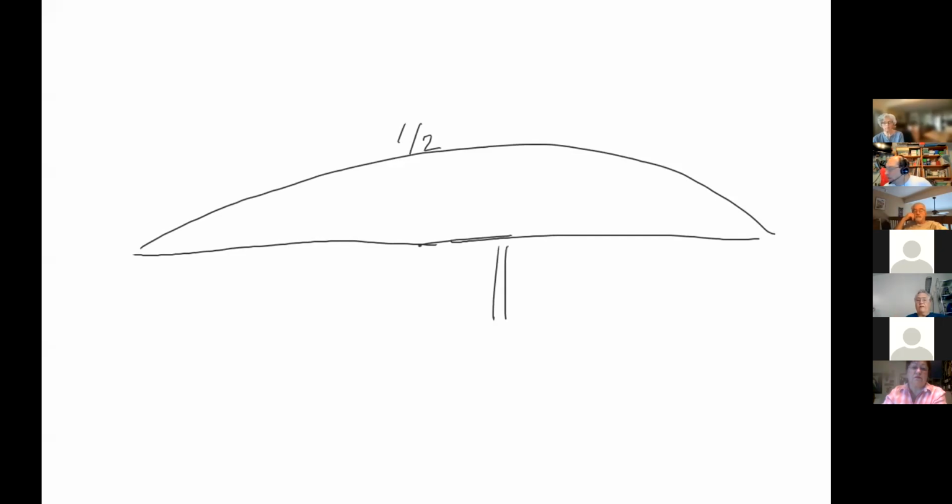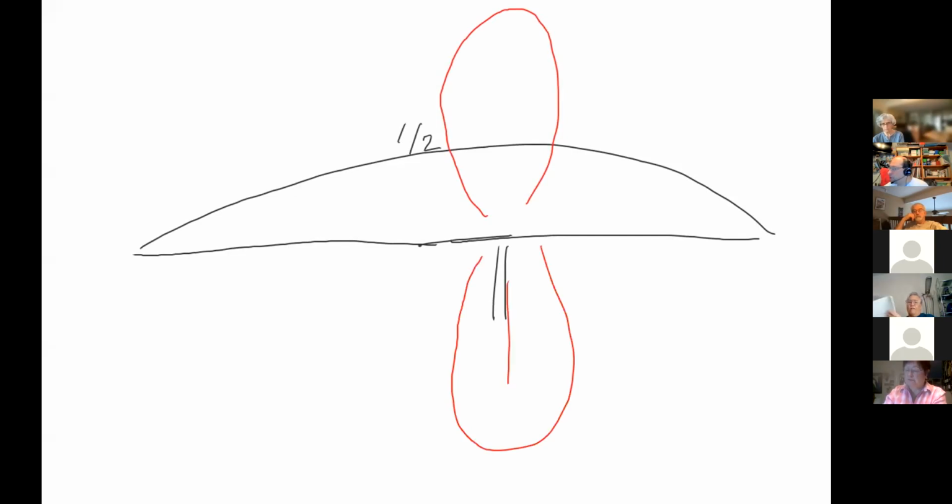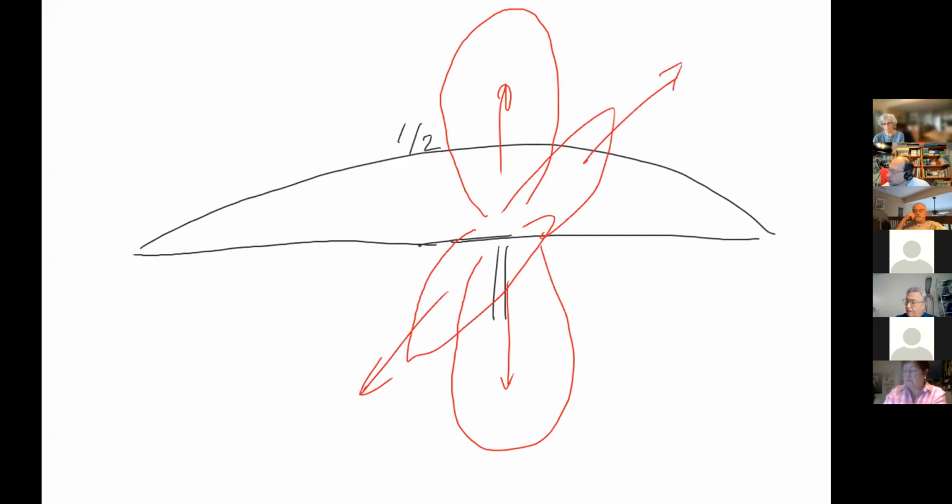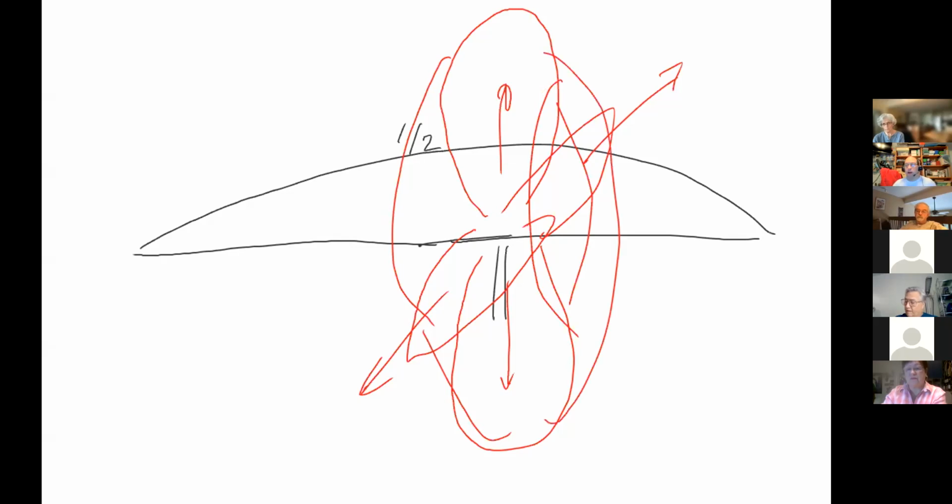Okay, now if we were to look at this antenna, this transmits energy perpendicular to the wire. So that would be straight up and straight down and out of the page and into the page, basically forming something the shape of a donut around the wire. So because it forms something in the shape of a donut around the wire, how much goes this way along the axis of the wire? If you look through the hole of a donut, how much of the donut is in the hole? Very little. None.